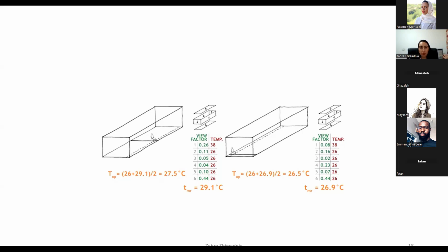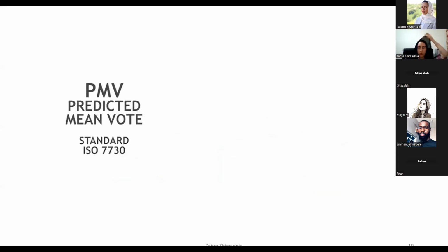And about the PMV, predicted mean vote, to take into account this effect, the European standard EN 15251 on comfort temperature to be maintained in heated and air-conditioned spaces refers to the operative temperature, not to the air temperature. The PMV model derives from thermal comfort surveys carried out on a large group of people exposed to the same environment.